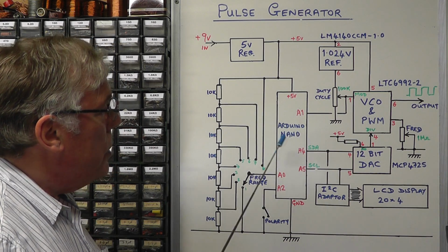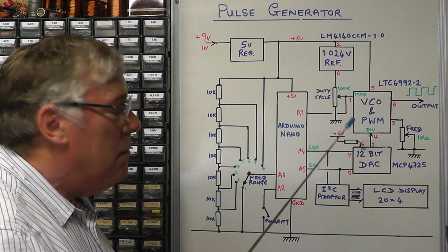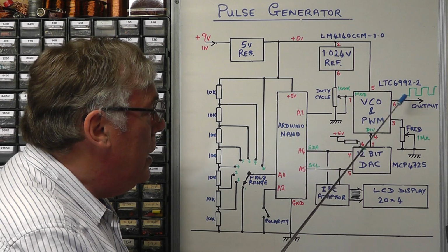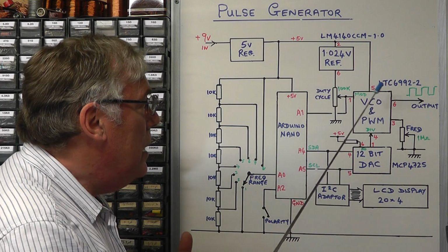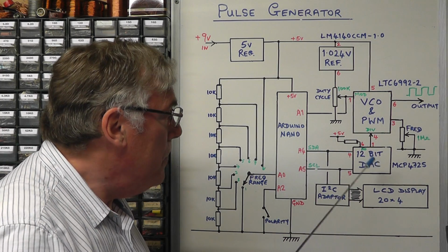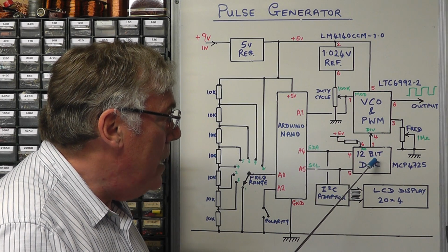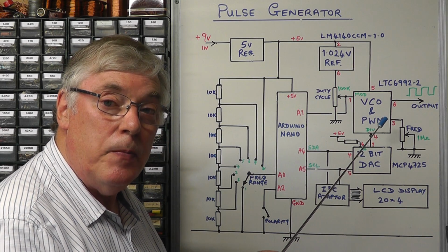Now, in addition to those controls we have for the oscillator, remember we can also alter the polarity of the pulse coming out. We can either have it going positive or negative, and that's done by altering the most significant bit, remember, of the information that is used for the programmable divider inside the IC.